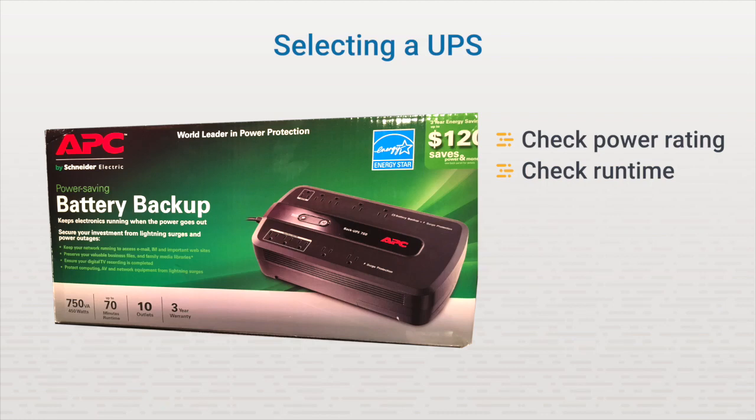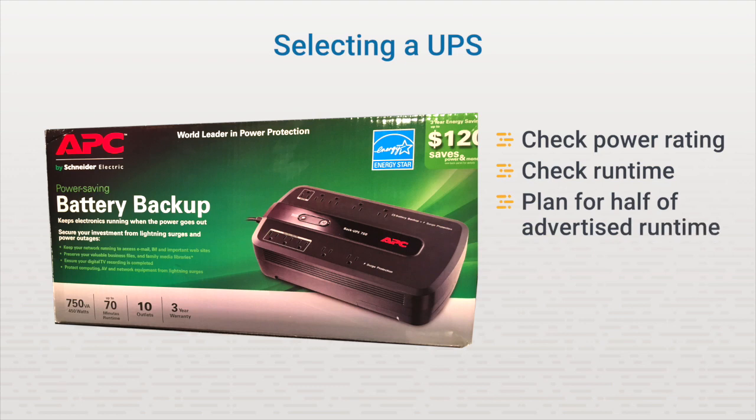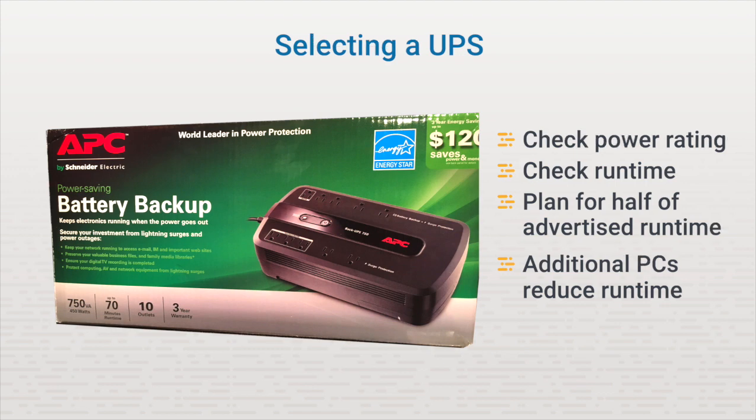But be aware that these time ratings aren't very accurate. A general rule of thumb is to plan for about half of the time advertised and use the rest of the time as a cushion. Also, if you plug more than one PC into the power supply, then you need to cut the amount of time in half again. Keep these factors in mind as you choose a UPS. Be sure you get one that will provide the power you need for as long as you need.